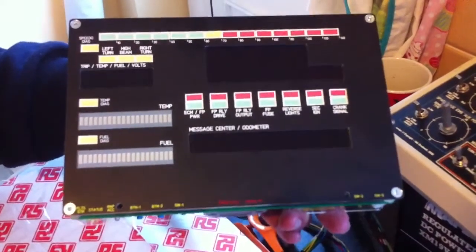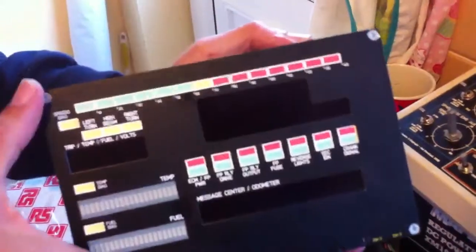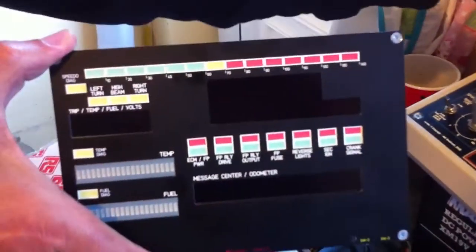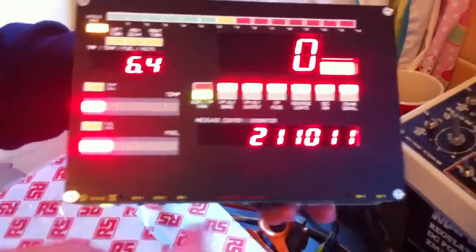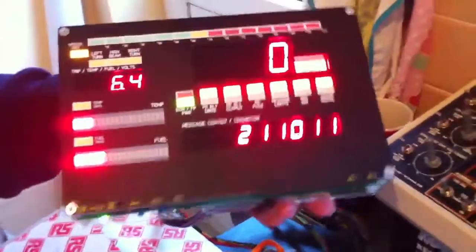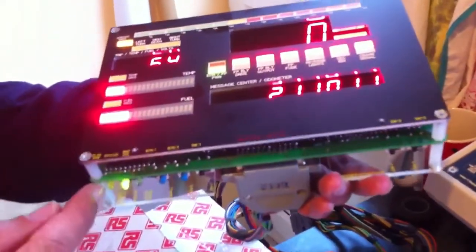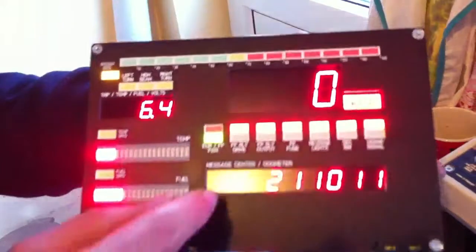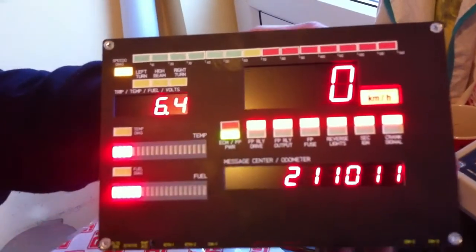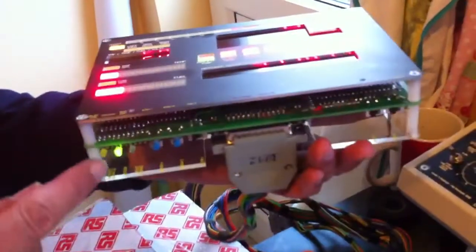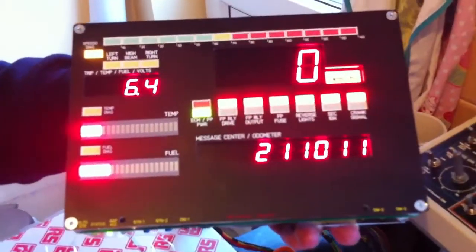So we're going to go into normal running mode by switching switch number 1 into the off position. So switch number 1 in the off position, power the unit up, and we'll go straight into normal running mode. There's no faults currently being detected by the unit, as indicated by the fact that the status LED here is green. That means no current faults exist. There's no F icon here, which means that no faults have been detected this journey, and the yellow LED is off, meaning no faults have existed in the past 64 journeys.